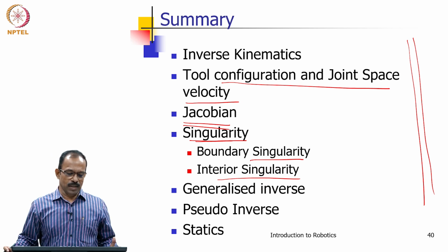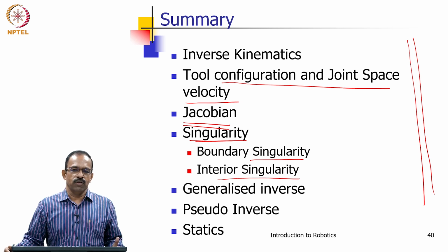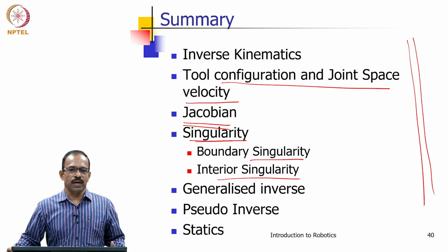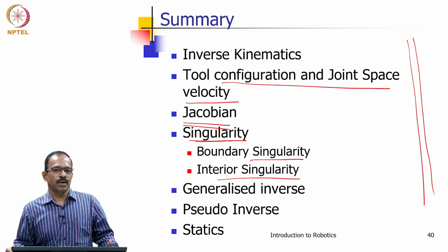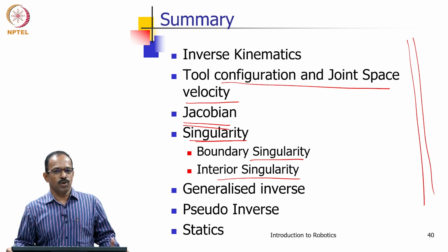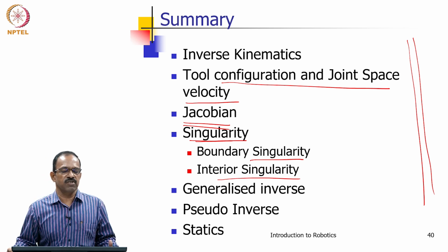After going through the physical elements of industrial manipulators, the types of joints and configurations, we started the kinematic analysis. We talked about forward kinematics, how the position of the end effector relates to the joints, and then inverse kinematics, where if we know the position of the end effector, we find the joint parameters. While developing this, we talked about DH parameters and the arm matrix, and then moved to differential kinematics.